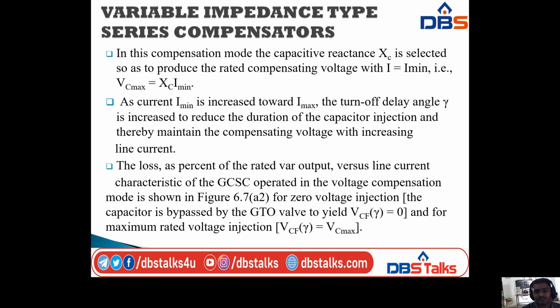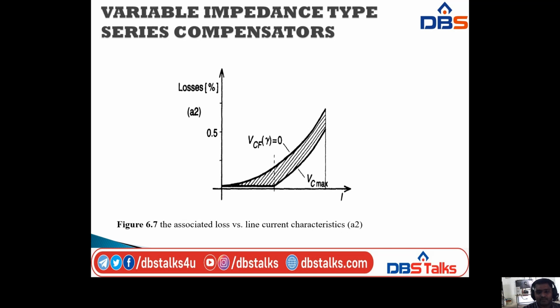The loss as a percent of the rated VA output versus line current characteristic of the GCSC operated in the voltage compensation mode is shown in the next diagram, that is 6.7a2. That is for the zero voltage injection, and for the maximum rated voltage injection, that is VCF of gamma equal to VC maximum, and VCF of gamma equal to 0. So this is the graph of loss versus line current, the diagrammatic representation of that explanation. Here we have VC maximum and VCF of gamma equal to 0, and I am taking losses in percentages from 0 to 0.5.